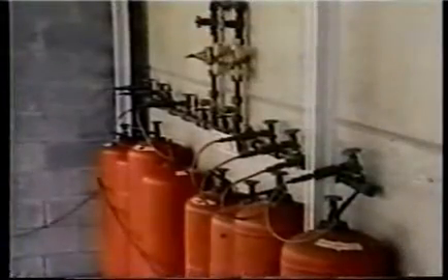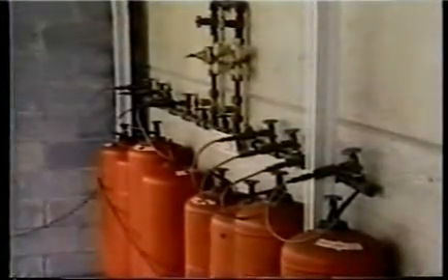If additional gas volume is needed for a particular application, cylinders must be manifolded together like this. Remember, adequate gas volume is essential for the efficient and safe operation of all gas apparatus. Acetylene cylinders must always be stored in an upright position in order to keep the liquid acetone properly contained.